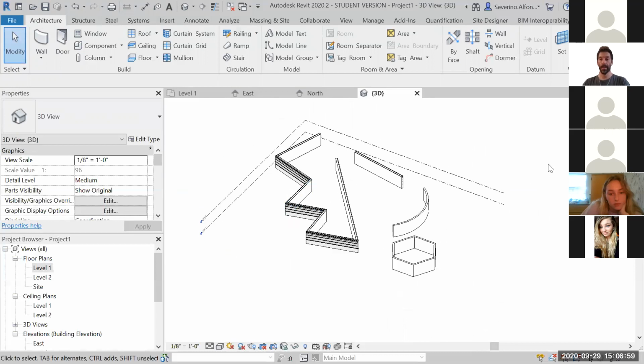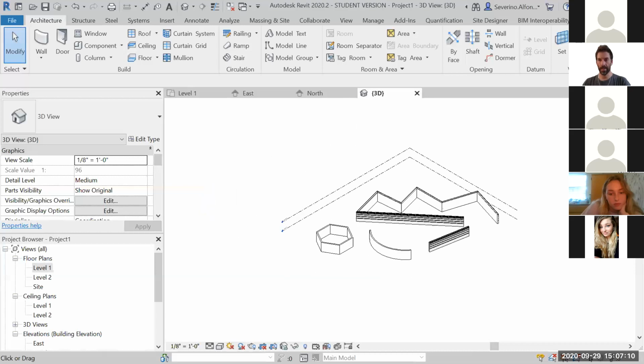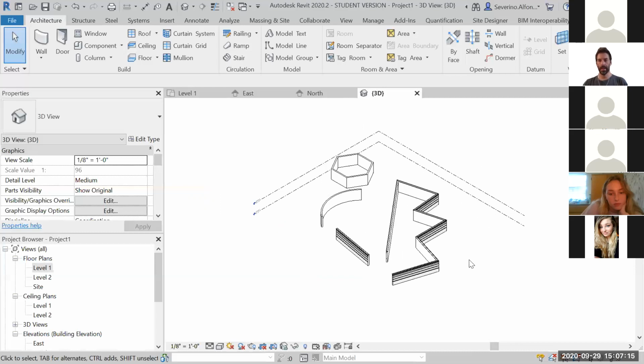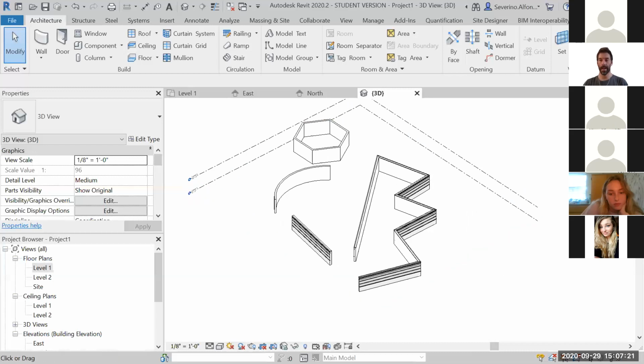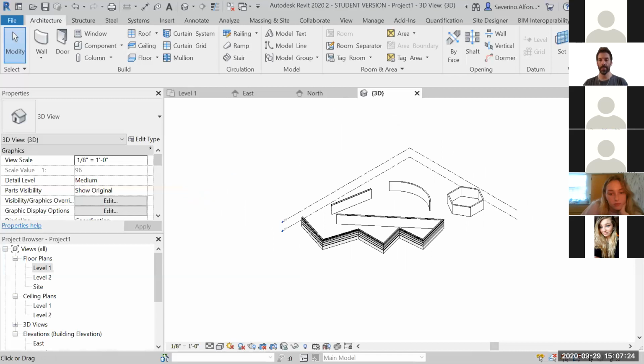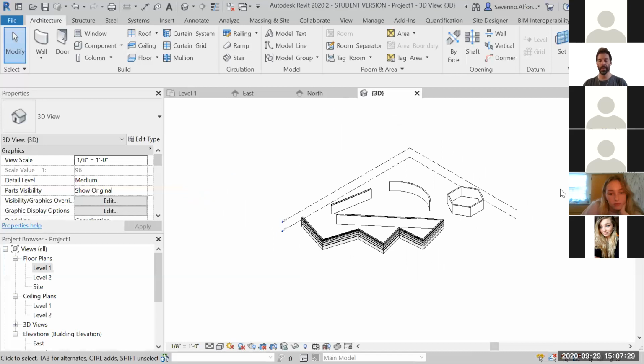Some people like to use the little box here. By clicking on the little corners, you can drag it right and left, and you can go to a particular view. For example, if you click on this little box just once, which is the corner of that box, this is exactly an isometric view of this project. This is another isometric view. You can have an isometric view from the bottom. You can have elevations as well, but I'm not a fan of this feature, though some people love it. So it's up to you to decide if you want to use it in general.